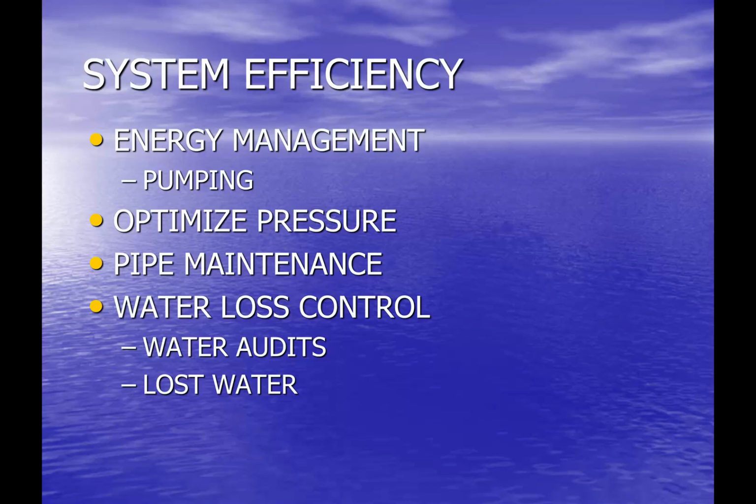One of the important things, though, is that you do want to meter any internal uses. If you're flushing water, you want to meter that. If you are using water at your own facilities, you want to make sure you meter that so you can account for it. Because ultimately, all of that, when you start looking at those losses, it can help you identify that, hey, maybe we have a leak somewhere. Maybe we have multiple leaks. And there are approaches to go out and try and find leaks that you didn't even know existed.